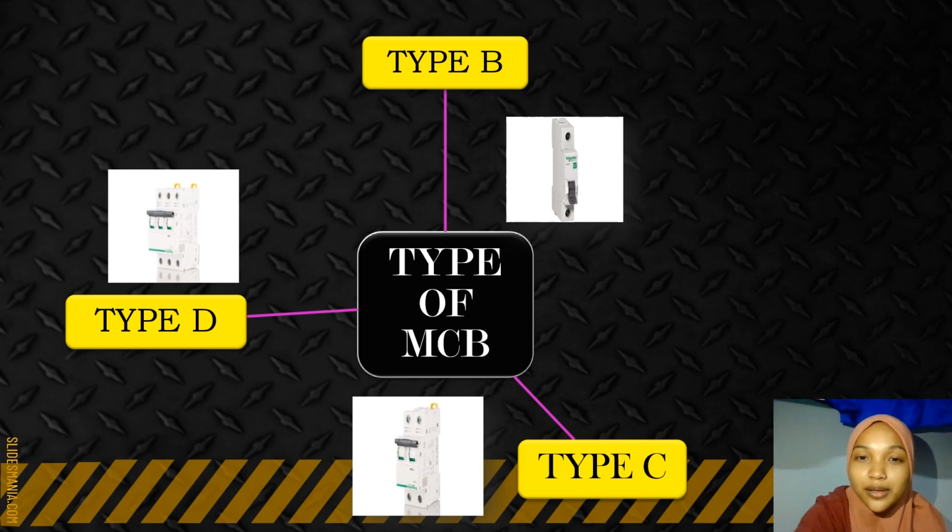Type C circuit breakers are used for more powerful electrical devices, where any surge is likely to be higher, typically in commercial and industrial environments. The Type D MCB is the least sensitive type, only activating when current surges to between 10 and 20 times the recommended maximum. D-rated MCBs are built for heavy-duty commercial and industrial devices where very strong current surges occasionally occur.